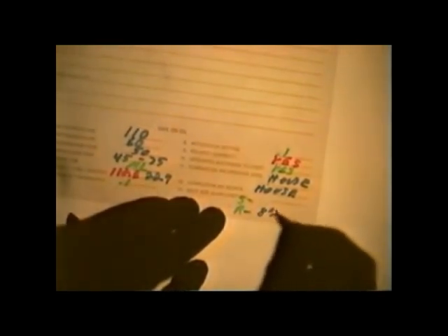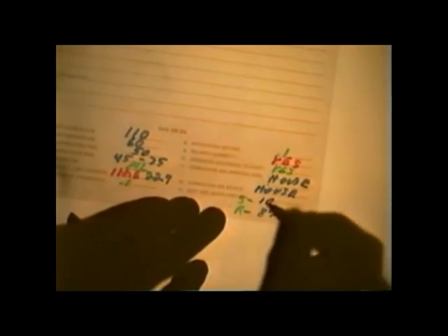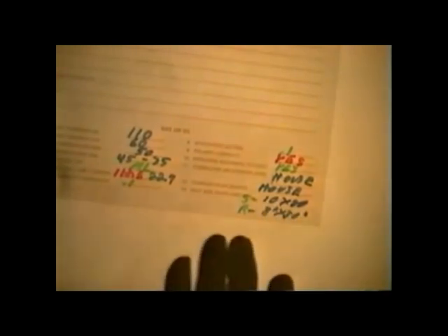8 by 20. And then a 10 by... a supply plenum? 10 by 20, or supply plenum, that would be the furnace size, but 10 by 20 for the branch lead. Okay, so the supply, we want to put down 10 by 20 branch, or for the extended plenum? Yes. Okay, that's fine. And again, it really doesn't make any difference. The point is you still have to be able to explain it. And in some cases, your supplies and your returns are the same. In some cases, the returns are bigger than the supplies. Okay? Let's just talk about that a little bit.